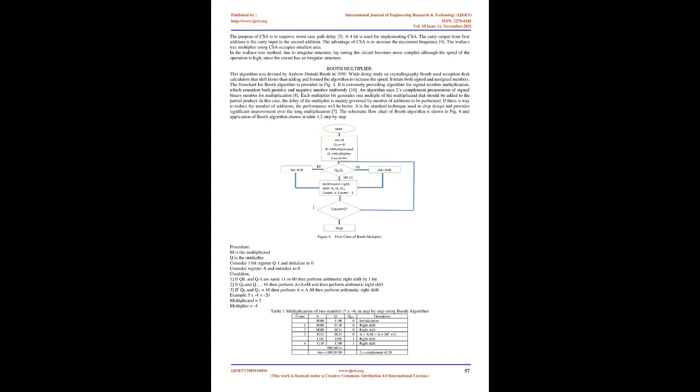A half adder is used in each column where there are 2 bits and a full adder is used in each column where there are 3 bits. Any single bit in a column is passed to the next stage in the same column without any operation. This reduction procedure is repeated in each successive stage until only 2 rows remain. In the final stage, the remaining 2 rows are added. After completing all the 3 stages we get an 8-bit output. The schematic example is shown in Fig 2.